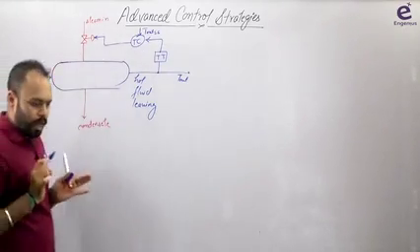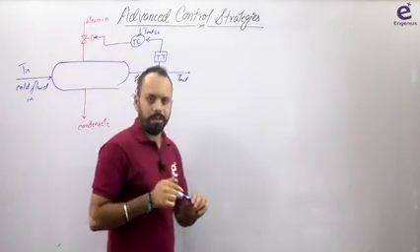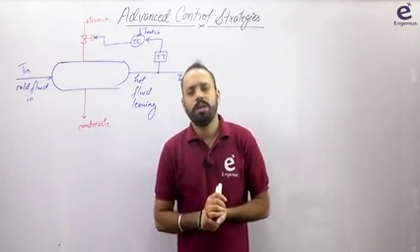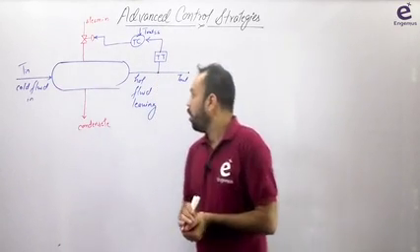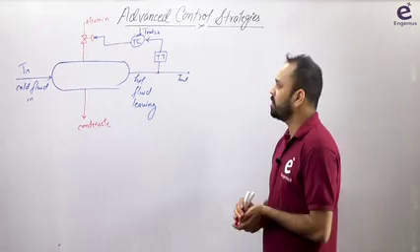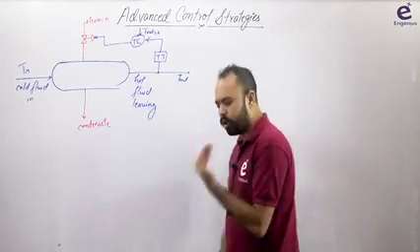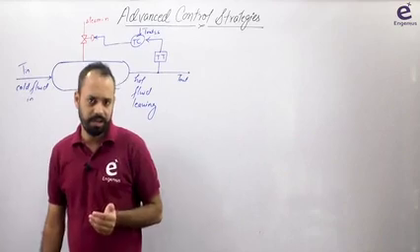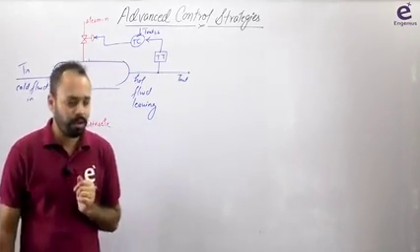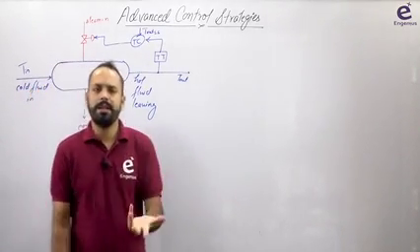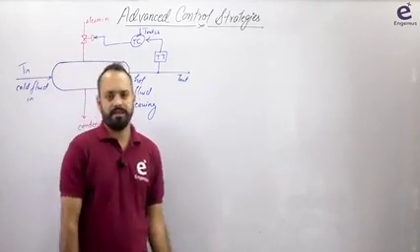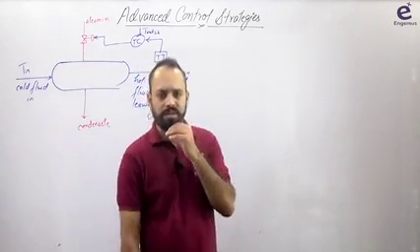I told you that for deciding the nature of controller, you must know the nature of valve, right? Of course this is steam. I told you that even if they do not mention, then in some cases I can use the fail safe criteria. I explained very well what fail safe was. In some cases suppose they did not tell what the nature of the valve is. So you can use the fail safe criteria, and I told you the meaning of fail safe